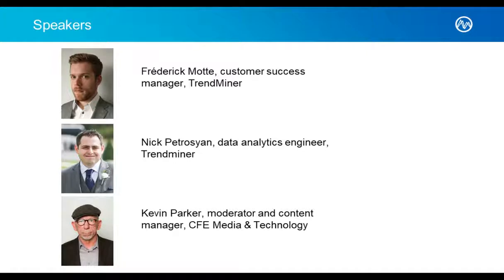Yeah, so our APIs are wide open in TrendMiner, so it's really easy to call TrendMiner's functions from Python or also to post and send things to TrendMiner. But it depends how complicated your purely rule-based notifications are. There's a lot of capabilities inside of TrendMiner where you can set up different rules, like with a value-based search, you can set up rules like I want to get an alert if this pump is on and the temperature is greater than XYZ for more than 2 hours. Send me an alert, send me a notification.